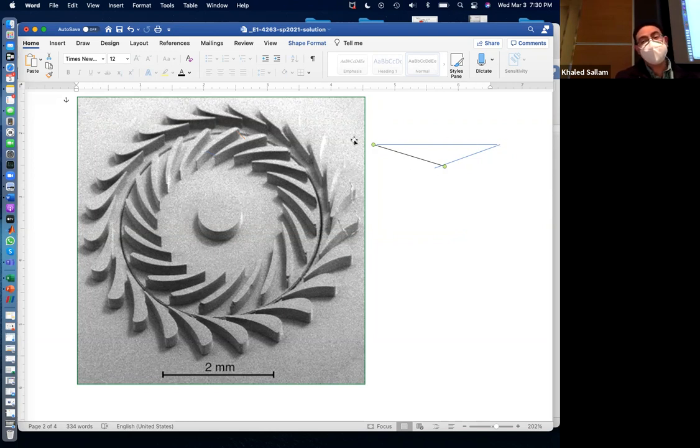So if V is like this and U is like this, W must be up or down? It's going to be down. That's correct. Why? W has to be down. Yes, because of the equation U plus W equals V. So knowing that U has to be like this and knowing that V has to be like this, W has to come like this from the velocity triangle.